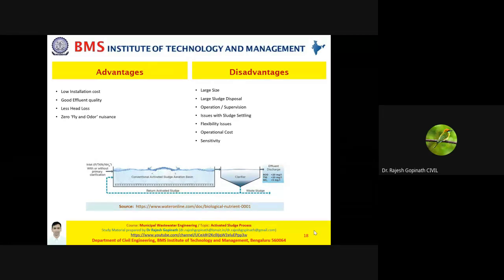If you're looking at trickling filters, the bacteria removal is only 80 to 95%, but the activated sludge process can help in removal of bacteria by 90 to 98%, in terms of the percentage of the original.